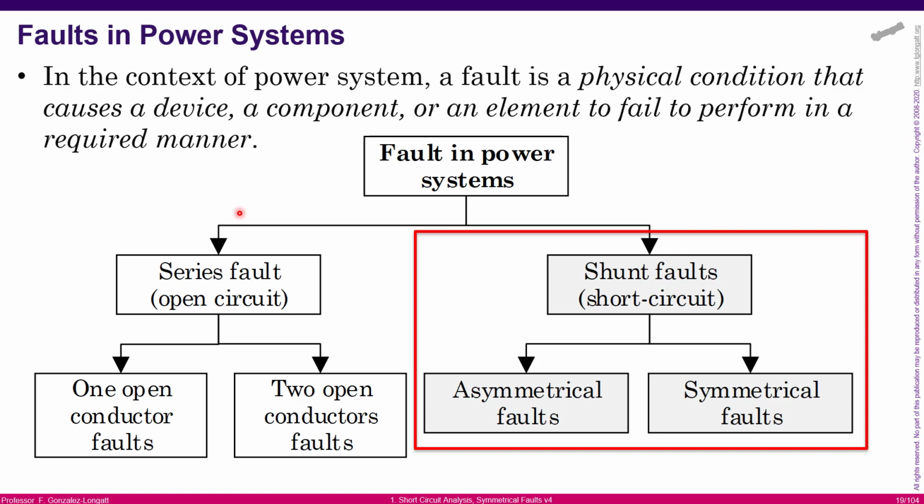On the other hand, I will not cover here the series faults. Series faults receive the name open circuits. If we have a three-phase circuit, we have two options of open circuits. A single line open, or one open conductor, and the second option that is two open conductors. Okay? Okay, let me keep going here.